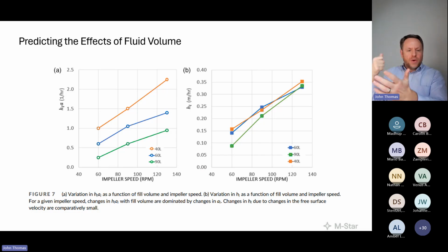That's where I hit that point so hard. Because if I did not have a well-stirred headspace and did not isolate the effects of headspace mixing in my HLA, this would be nuts. This wouldn't be trustworthy. When we've gone through the rigmarole of isolating headspace mixing effects to make sure we are reliably targeting HLA, it goes up. And I'm calling it HLA because it's not KLA. It's a different model and a different transport path.